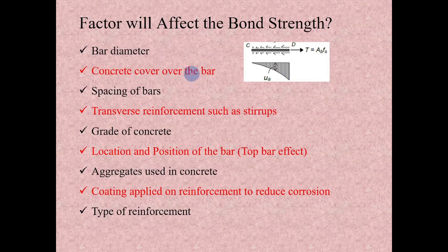Another factor is concrete cover. Let us draw a section something like this. If I have a rebar here, if the cover is more, the concrete can take more load before it cracks. So if the cover is more, the bond strength will be more.